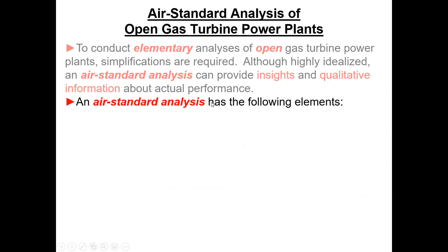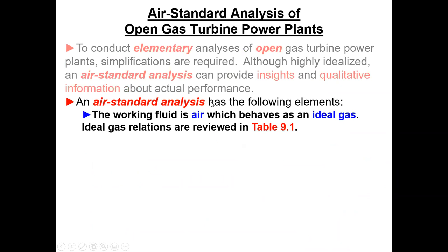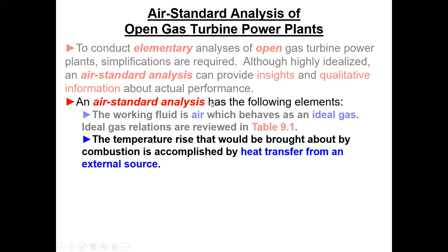Okay, so then, to start off, make it as easy as possible, we do what we call the air standard, which is more simplifying assumptions to make the analysis simpler. Okay, so the air standard analysis assumptions are: working fluid is air, which behaves as an ideal gas. So you get all the ideal gas relations.